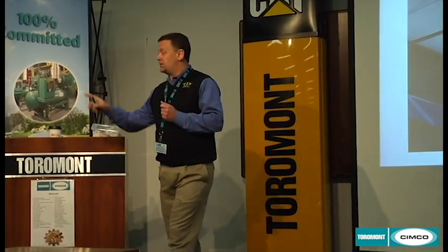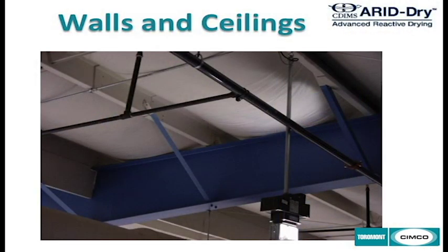Believe it or not, even though your building may have a solid wall, there's actually permeance that's going on through the material. Depending on what it is, moisture can actually migrate right through a solid material. It moves on vapor pressure differential, and that's a very powerful force. The material depends on how much permeance occurs. Steel doesn't have very much permeance, but concrete has a very high permeance. So be aware that your building itself is allowing moisture in.